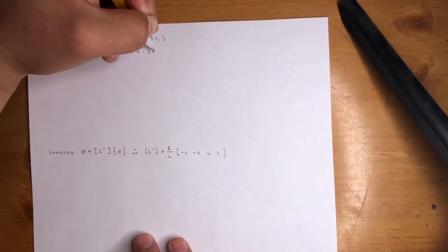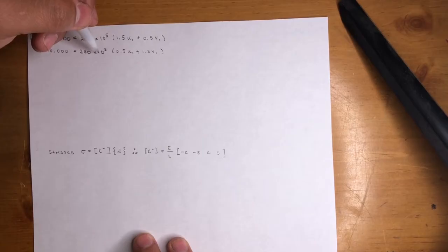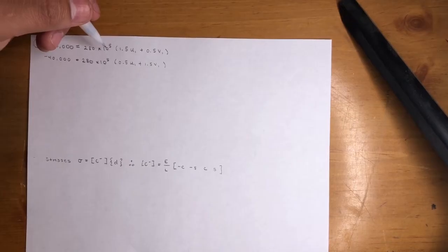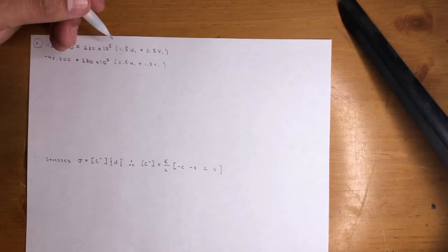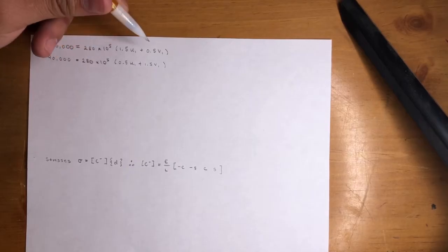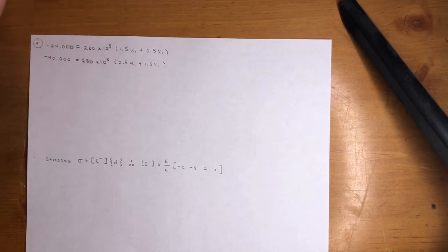But even if you forget it, once you get your answer, you should know something's up, because you're going to get a very high displacement, or a very low one, if you don't do that. It's usually something like 0.000, a small displacement. If it's extremely small, like 0.00000, you'll know you missed something here, just FYI.